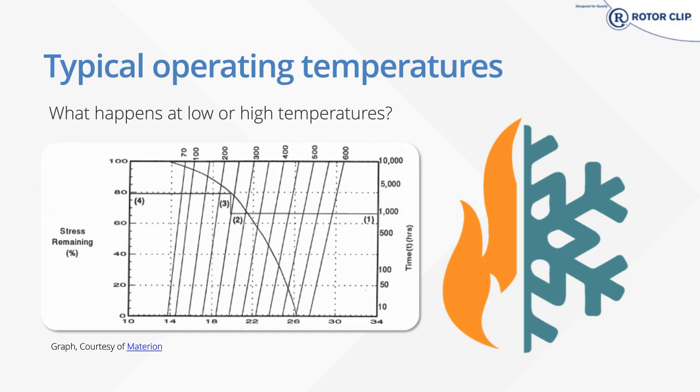Likewise for beryllium copper, you'll see similar performance curves, and same for stainless steel. At the other end of the spectrum, you have low temperatures. So around negative 100 degrees Fahrenheit is usually what we call out for most rings. And at this level, impact resistance is greatly diminished. Brittleness sets in, and there's a danger of fracture.